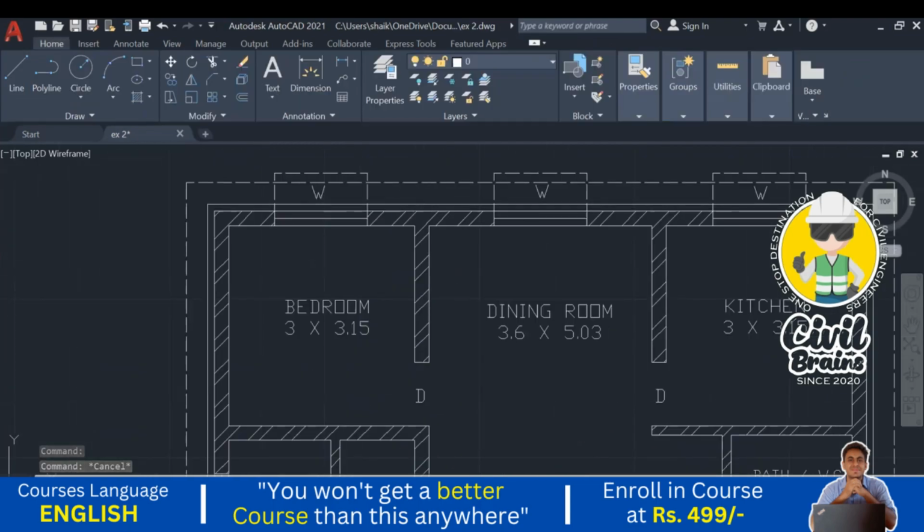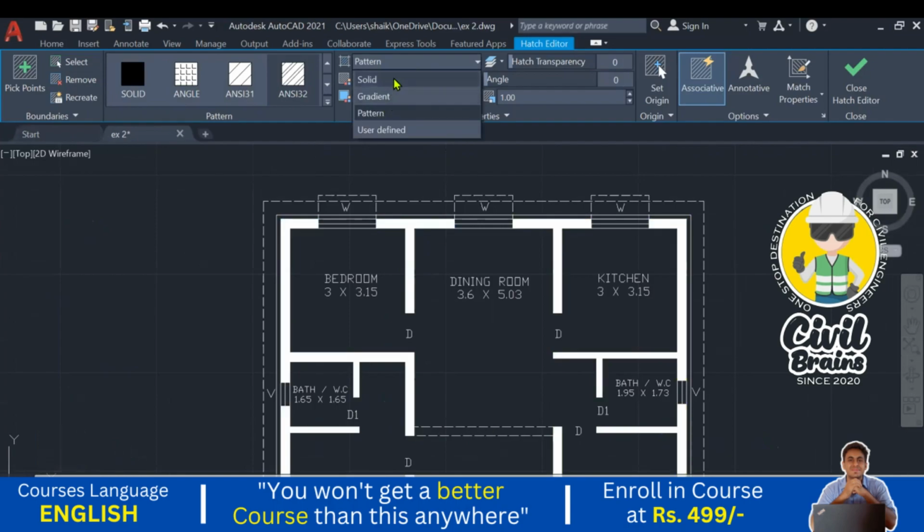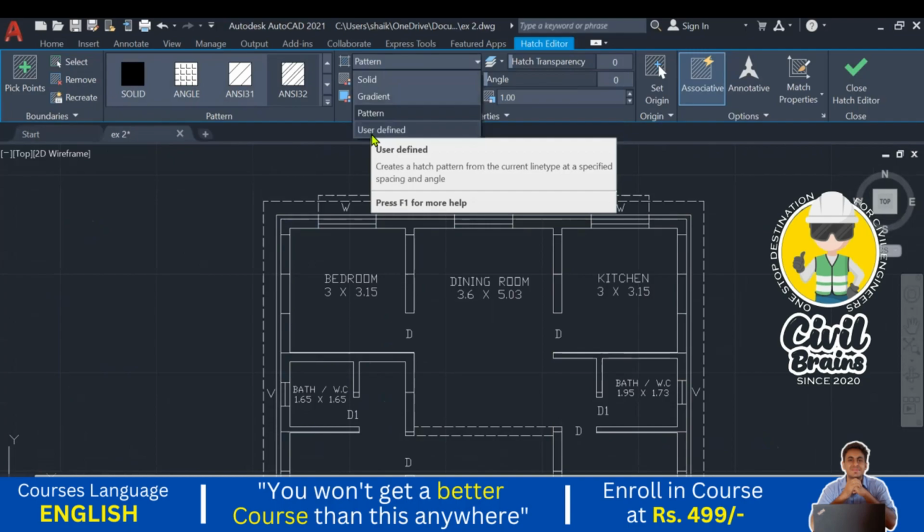Okay. Next, I just go to the hatch command. I just click on the hatch. So the hatch command will open, and here you can see this one: patterns, gradients, and solids. Here you can see solid. If you click, it will come solid. Gradient, if you click, it will create gradients, patterns, and define.